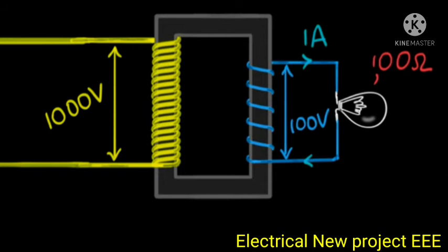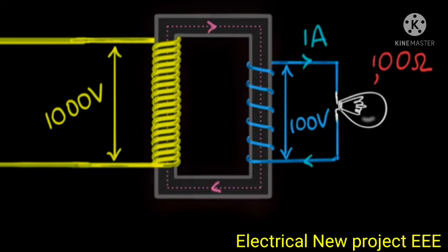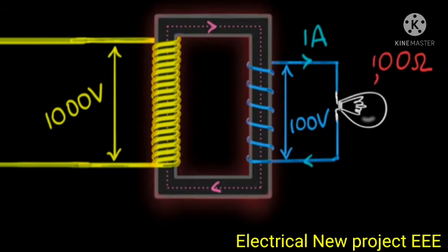And that's a big if, because in reality, there will always be energy losses. For example, you might recall, due to the fluctuating current, there will be a fluctuating magnetic field in that ferromagnet. And turns out, the fluctuating magnetic field generates heat in the ferromagnet. We call this the hysteresis loss. I'm not going to talk about hysteresis. What matters is there is heat generated.